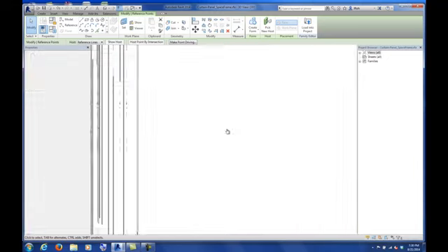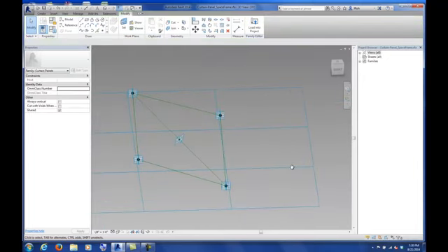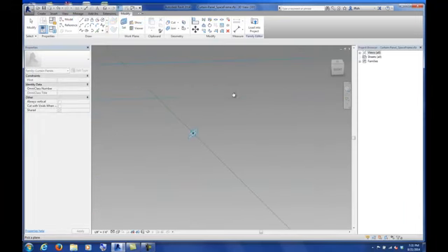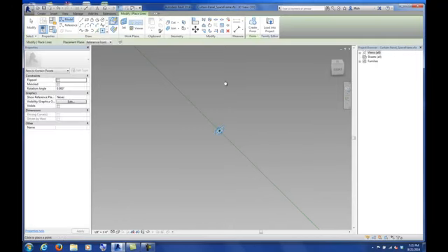And we got one last point to make. If I go back here where it says point element, this time before I place a point, where it says placement plane, I want to choose pick. And then I'm going to zoom in. Actually, that point never gets bigger. I want to pick, I'm going to have to tab over the horizontal plane of that point. You see what I'm doing there when I hit tab? That's what I want to pick with my left mouse button, and then I'm going to place that point, snapping it to the one in the middle.